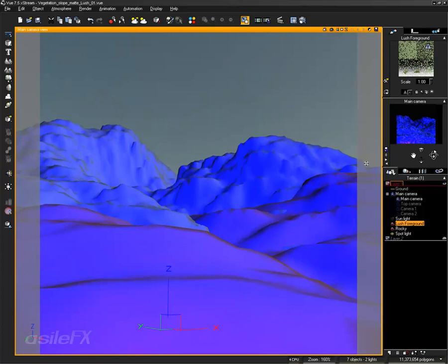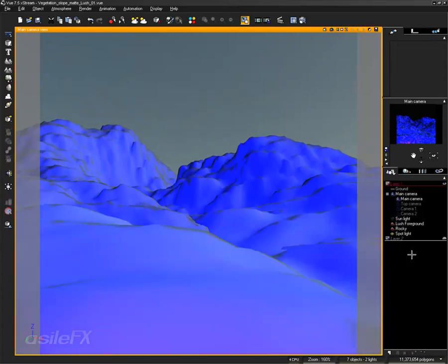So another thing you could do is take some of those ecosystem instances from the other scenes, delete most of them, but leave some of them in very key points of the scene where they really kind of stand out, just to add that depth. And all you really need to do is render out the animation of just the ecosystem with maybe an alpha and composite that on top of it. So it becomes a really good method to really separate everything because there are different anti-alias settings you need for ecosystems compared to terrains.